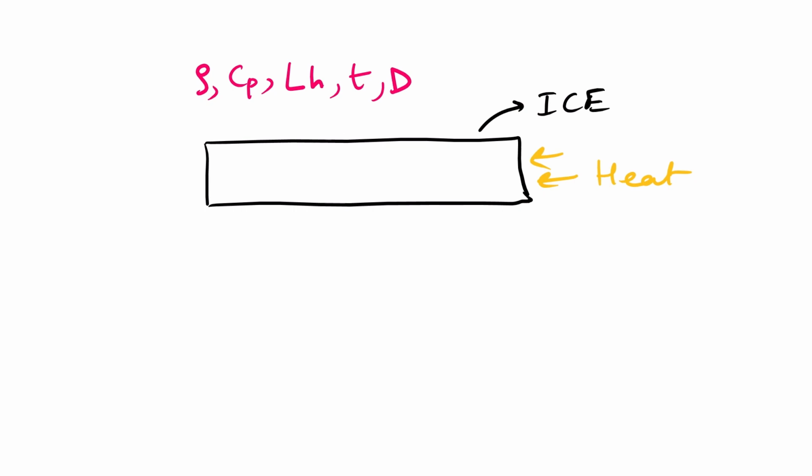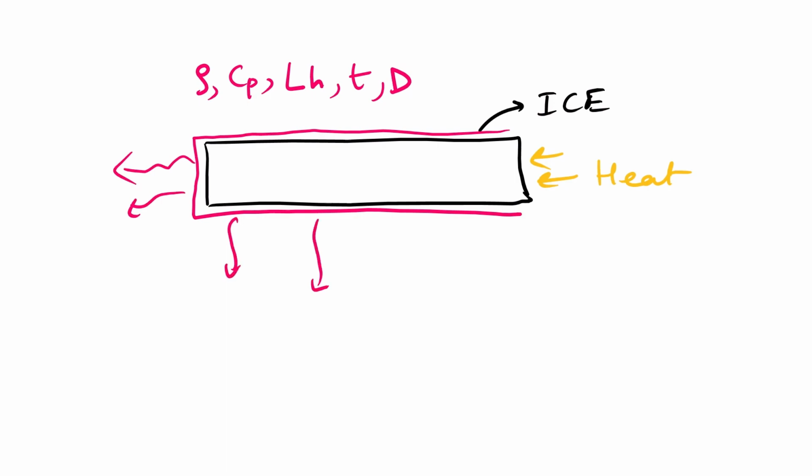Okay, so this is the main objective of our work, and in the meantime we'll also set an insulator on the other three sides, so that we do not consider the radiation and the other phenomena that are involved in realistic scenarios. So this is how the modeling workflow will begin. So let us jump into COMSOL Multiphysics and see how we can solve this problem.